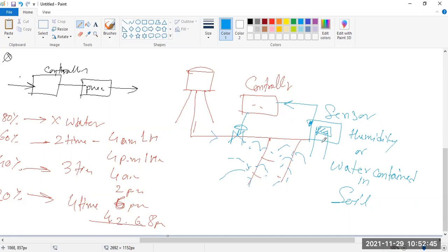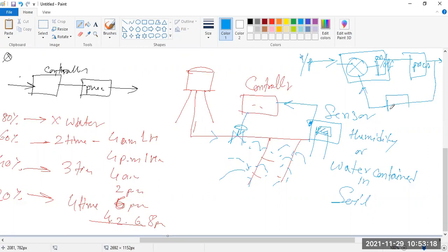But nowadays the automatic control system is used, because in this automatic system, look, what will be the control strategy or block diagram representation. There is an input, the input is only water, and here is a comparator, here is a feedback, here is the on off valve or your relay, and here is your process, and this is your feedback.